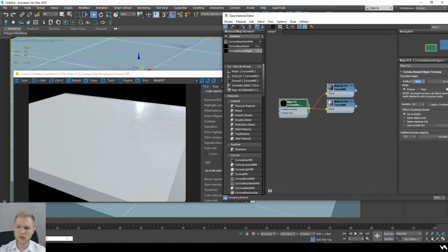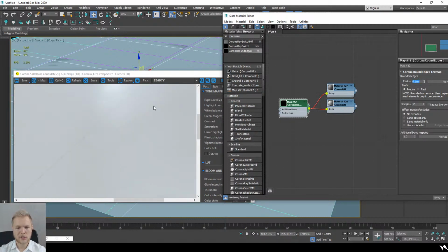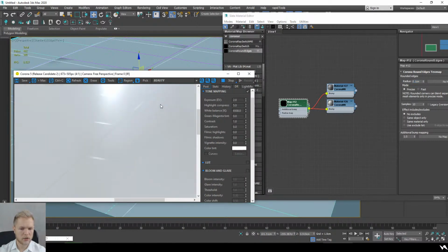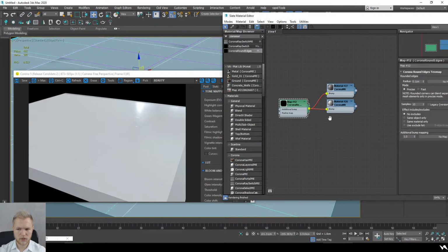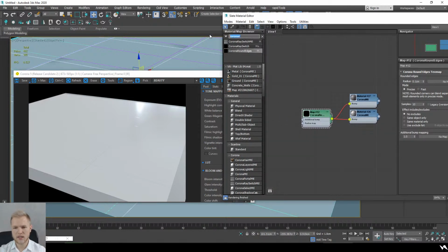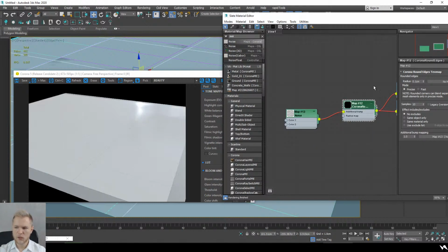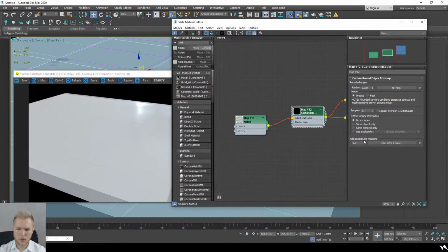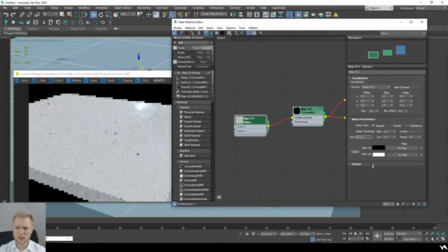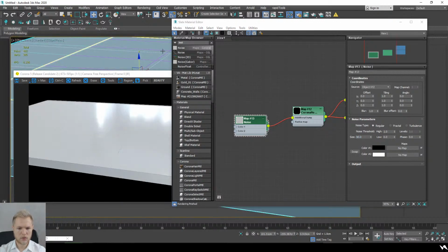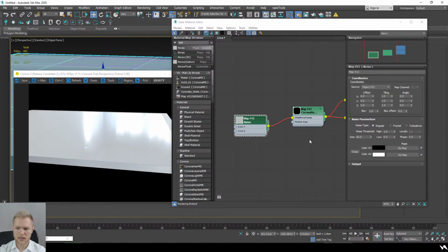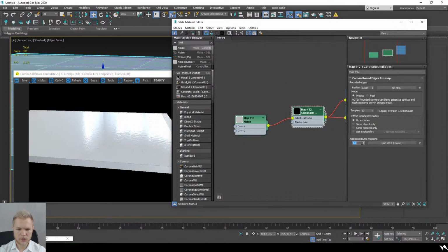Of course, don't be ridiculous, don't go for too high of a value. It's just 1 millimeter maximum for tiles, so you have this really subtle effect. And of course, the bumps, as I said, as noise. So remember, when you add this as additional bump, you may want to change the additional bump power to, let's say, something like 1.5. So it's really going to be small and really subtle. Then the size of this thing in the end, we're just going to change this to be subtle again. So don't be ridiculous when it comes to those values.